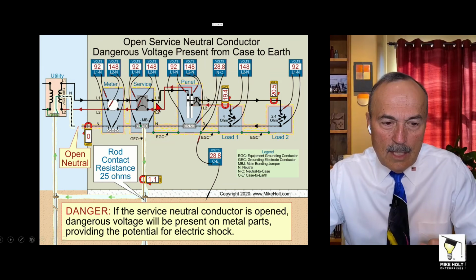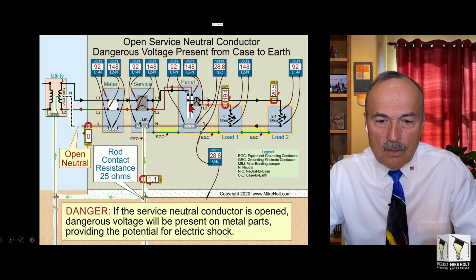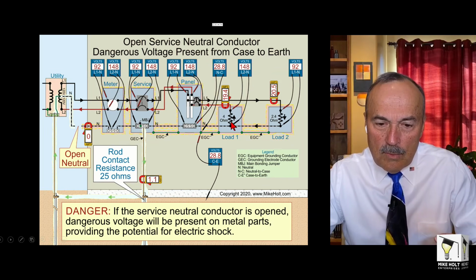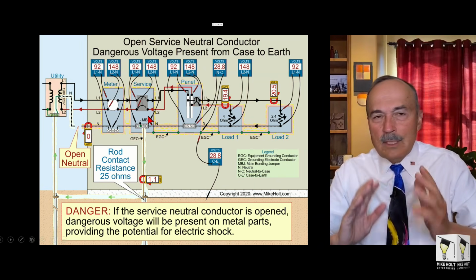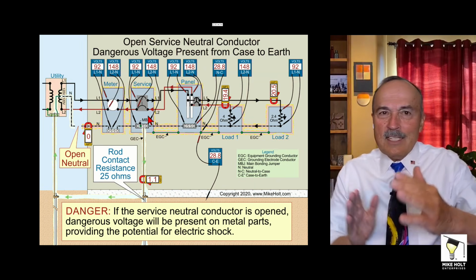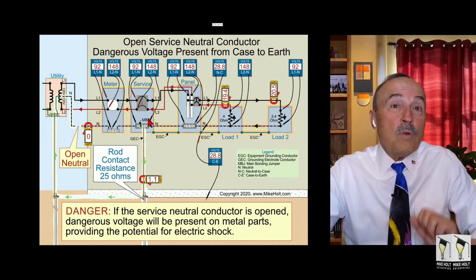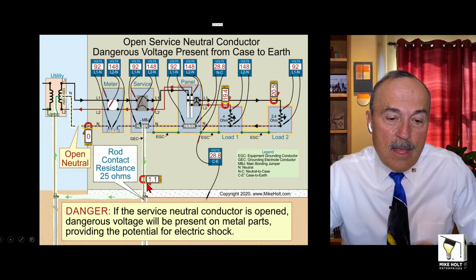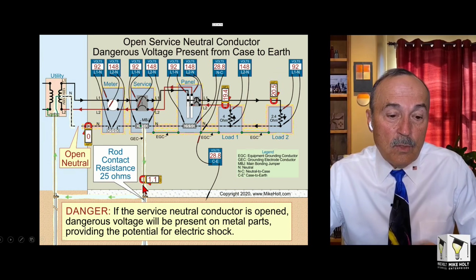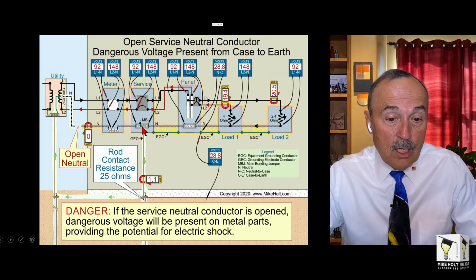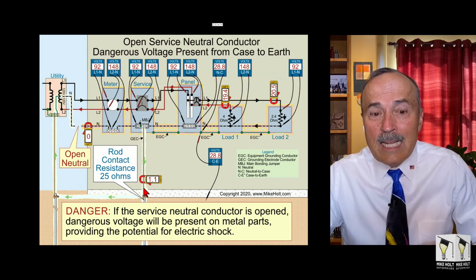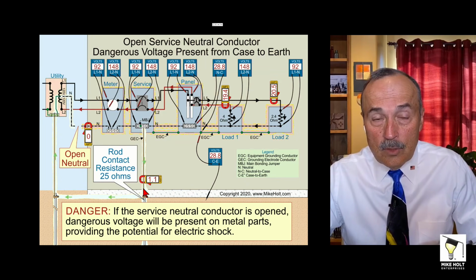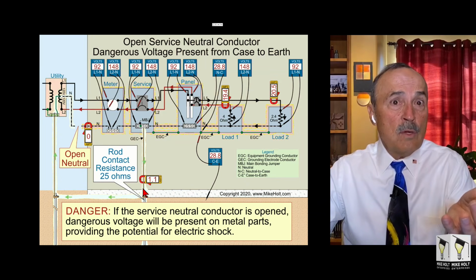And those, actually, both arrows should be going both ways. Let's have arrows, Mike, going both ways. And the currents would be going down. It's kind of both ways. When you get line 1, line 2, electrons are actually going this way with the neutral. What I'm saying is this. The neutral current, which is not there because no neutral conductor, that current is going to be 1.1 amps on the grounding electrode conductor. So you put an amp meter in the grounding electrode conductor, you measure 1.1 amps.